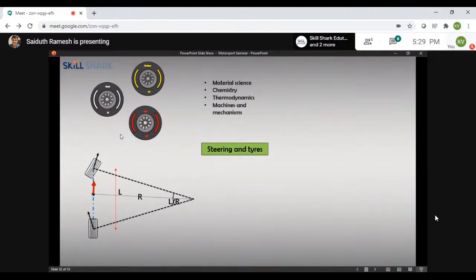If you're watching this webinar now, just put your hands together and twist them this way. You'll feel a sort of torque, a lateral force along the palms or wherever your contact patch is. Your tire moves in one direction, it's rolling, but that contact patch points in another way. I've made a small indentation here in the tire. So the more slip angle you generate, typically the more lateral force you generate, the better a tire performs.